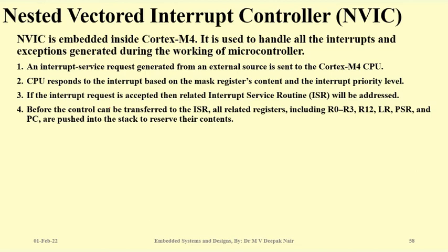Now the question is, before going to the ISR, the microcontroller should store some important data relevant to the current instruction it was doing, because the microcontroller has to jump from one memory location to another. So what is its current job? It has to store all the current job related data in some memory. Okay, so that is pushed. All the data related to the current instruction is pushed into the stack.